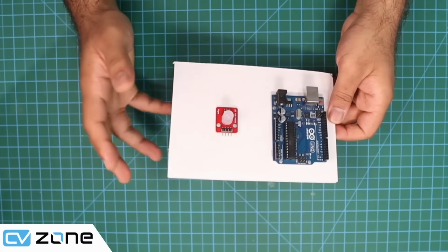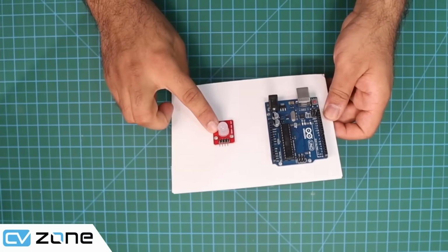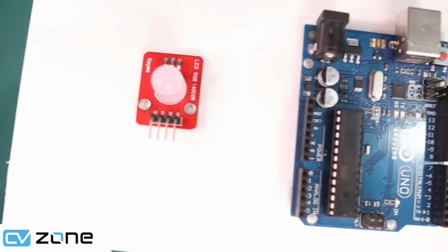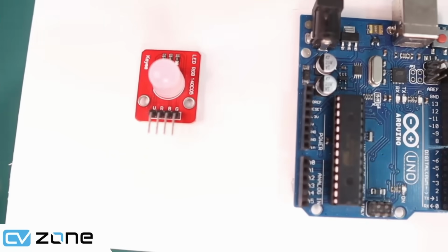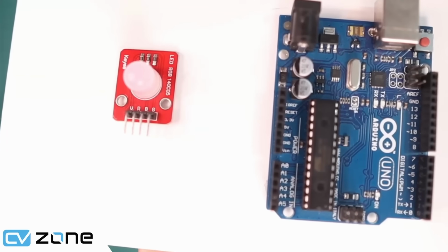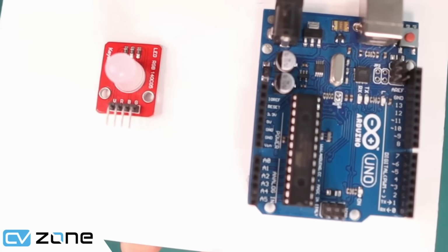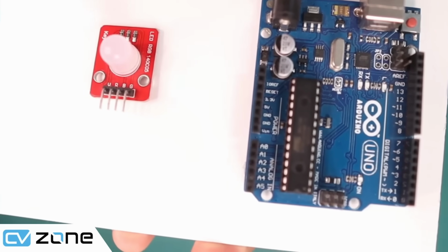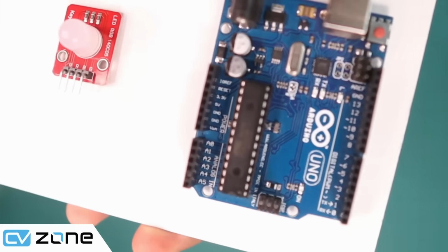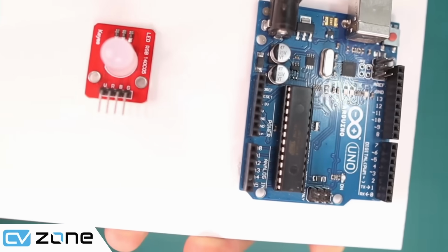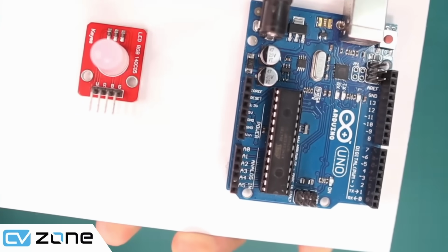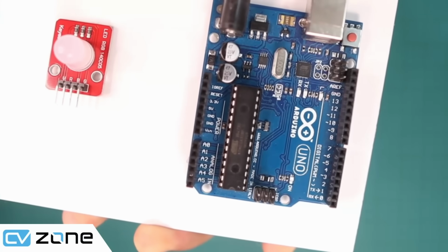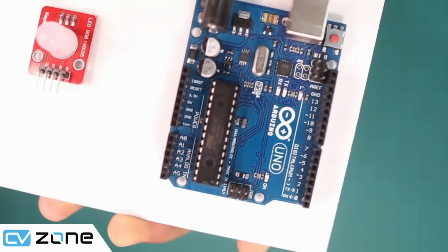So the first thing we will do is connect our LED light, which is RGB. Now you can see that here it has three negative pins for ground and then one voltage pin. So the negative ones are the RGB pins. If we give it 0, then it will turn on. If we give it 1, which is high, then it will turn off. So it is a little bit opposite to what we are used to. So it is RGB, and whenever we want the red color to turn on, we will turn it off at our pin connection. So it's a little bit weird, but we can get used to it.